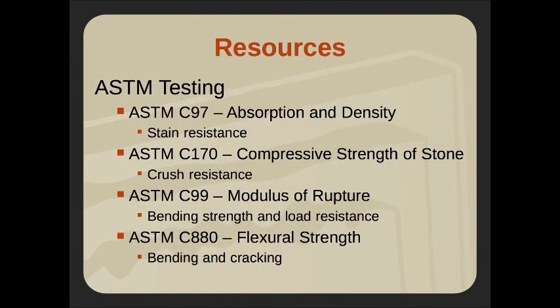So those are sort of the primary structural tests that we can do that give us a good idea that we're on the right path. And if one of these doesn't make sense, then we know we're not on the right path. The ASTM in the back, in the index of the DSDM, has the minimums for each material type with these tests, and I refer to that often. It's a great resource. So if we've tested a material and the C880 isn't hitting the minimum recommendation that the MIA has thrown out there, then we need to look at a different material.